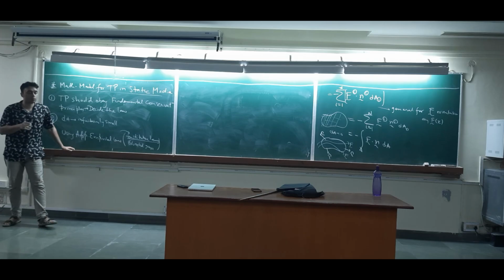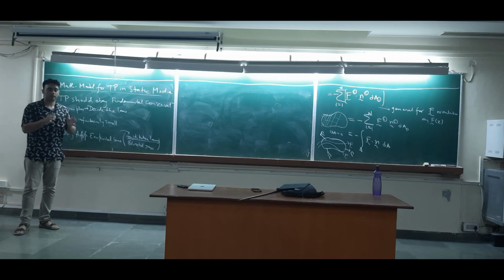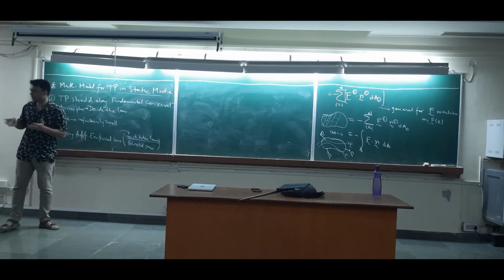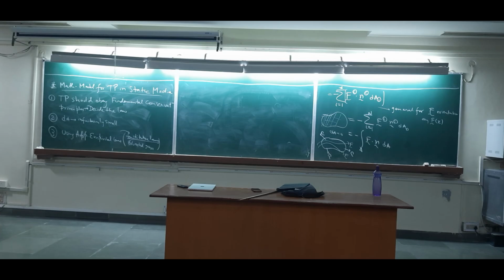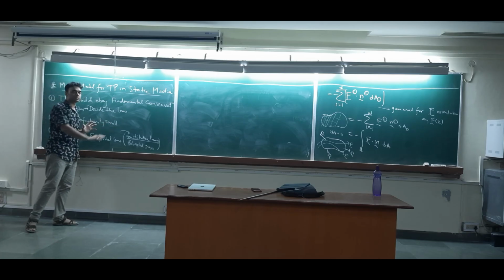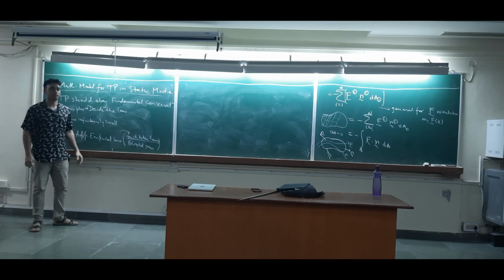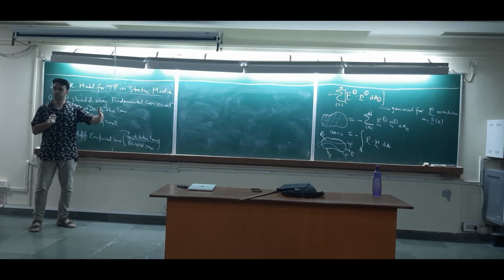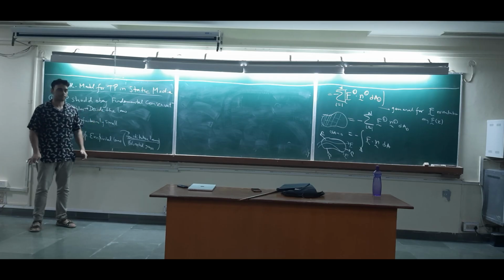If you are looking at heat transfer through a slab at nanosecond time scale, meaning you give 100, you give 50, and you want to study what happens at very early times, you have to take that relaxation into account, so you cannot apply your usual Fourier's law. So that's why it is important to know these are not fundamental laws, these are constitutive laws which are valid for a specific range of materials.